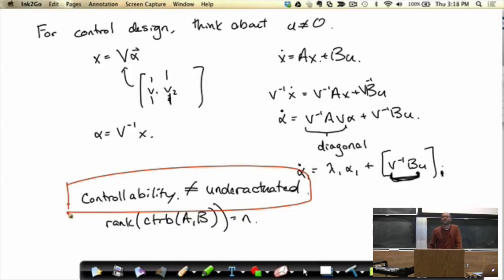If A is not PSD, does that mean the system is just not linearizable at that state? Right, so there's a question of, if you have zero eigenvalues in A, then there's a deeper question there that we're not quite getting to, but there's a question of how informative the linear system is about the nonlinear dynamics. In the case where you get zero eigenvalues of A, the stability of the linear system does not imply anything about the stability of the nonlinear system. I think that's what you're asking, right?